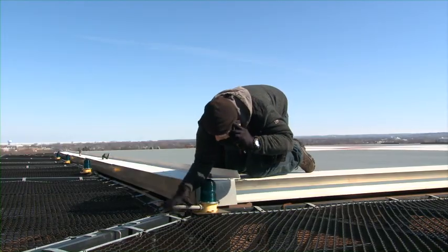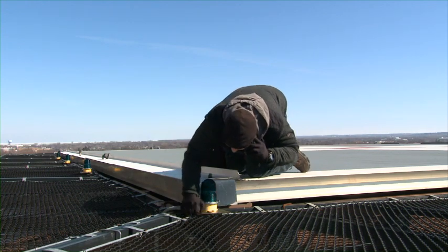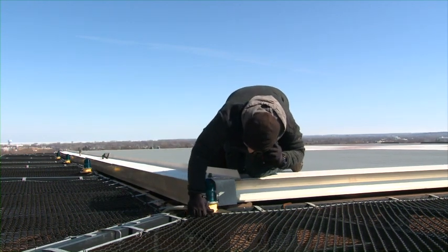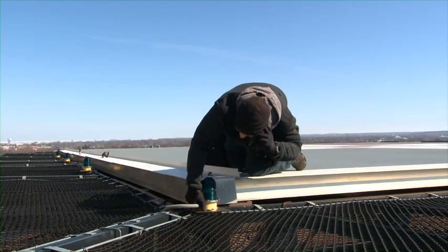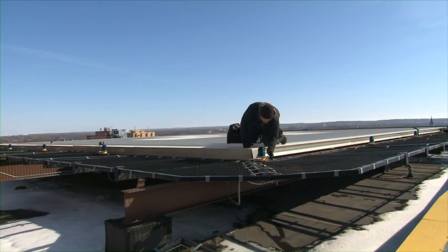When using safety nets for fall protection, they must be installed as close as possible under where you're working, but never more than 30 feet below the edge of a walking working surface. Safety nets should also extend outward from the edge of your work. It's important to consult a qualified professional when choosing the correct safety net system.